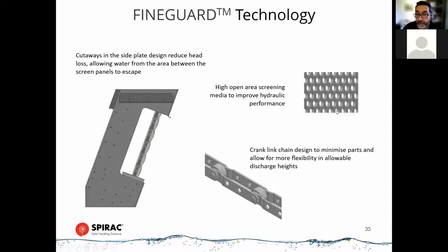Normally on a 6mm perforated panel, you would have what we call an 8mm pitch. So that's 8mm between the center of each hole. That's the optimum configuration you can have for a 6mm perforated panel, and that usually gives you about 51% open area, which is often specified.